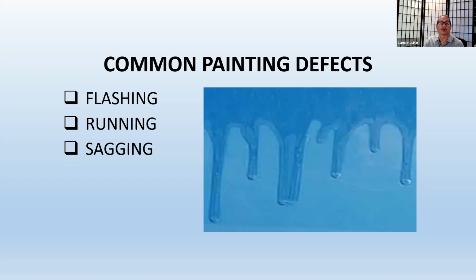If the wall is concrete and there's cracks in it, the cracks weren't filled, or it's spalling and the spalling area wasn't repaired, and you painted it, and then two years later a piece of concrete either cracks or falls off. And there's a claim regarding the paint: hey, you didn't do a good paint job. The painter says, well, no, I painted it correctly. It was the concrete that cracked. So therein lies the issue where you've got to bring in somebody else, a third party, to look at it and make a determination of who's at fault here.